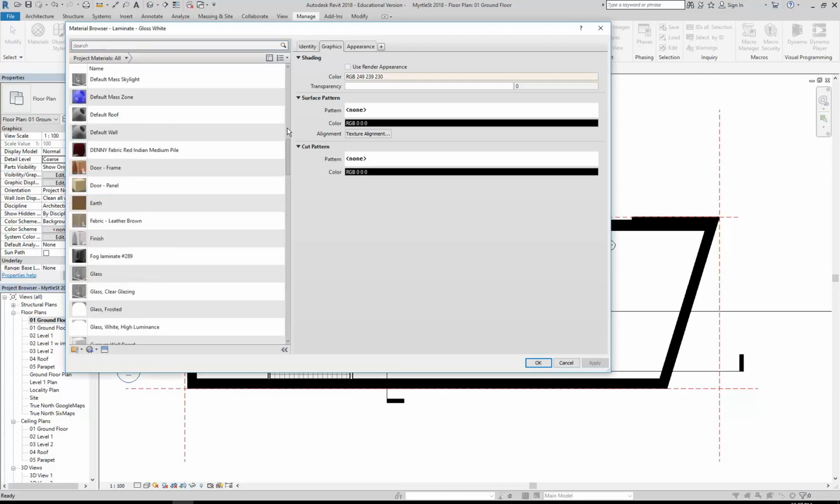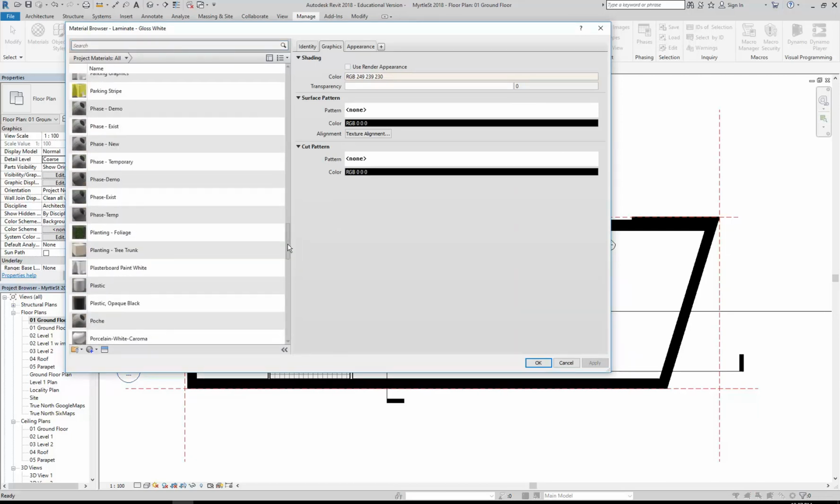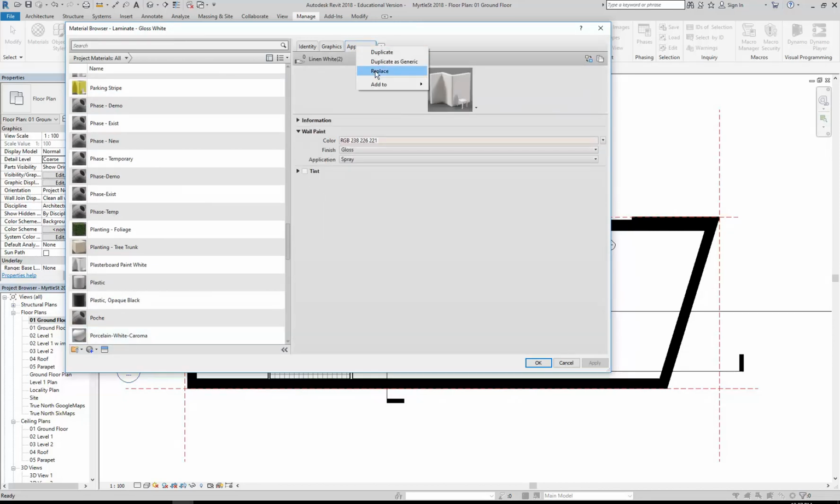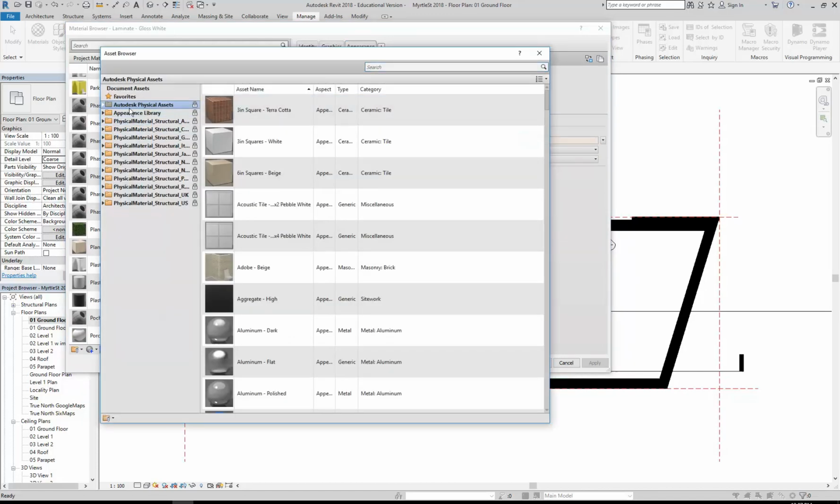In Revit, you essentially have this list on the left, which is the project materials. So that's stored in your project file. And then the render appearance is a separate library. And this might seem like a strange setup, but basically that's read only. You can't modify that. Even I can't modify it. It's deliberately left that way, so it's the same for everyone. No matter where you go, every time you use Revit, that is a locked material library. It's just meant to be a starting point, and then you can bring materials in from there to your project, and that's where you modify them.